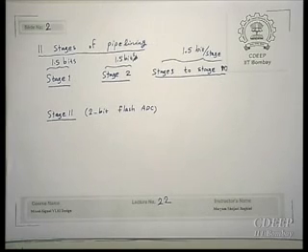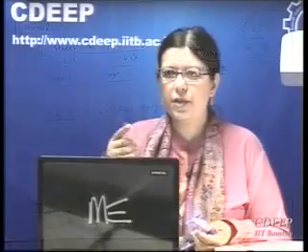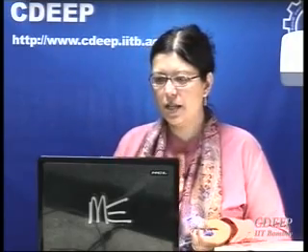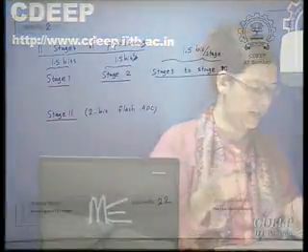By the way, there is a notation which actually is not correct. That is called digital error correction. Of course this is used, that is okay. But this digital error correction is not calibration or something else. This is the same thing that we discussed before. Like in pipeline ADCs, they generate redundant bits, and then out of those redundant bits, they generate main bits. So this logic sometimes is called digital error correction. In this paper, they particularly call it by the same name, but this is the same logic that we already have.